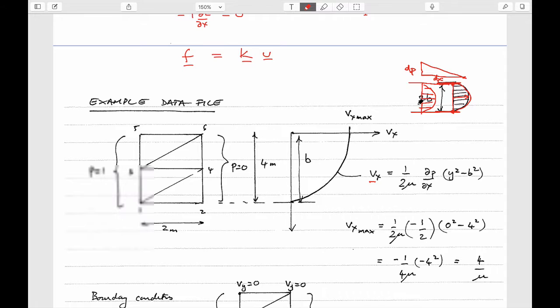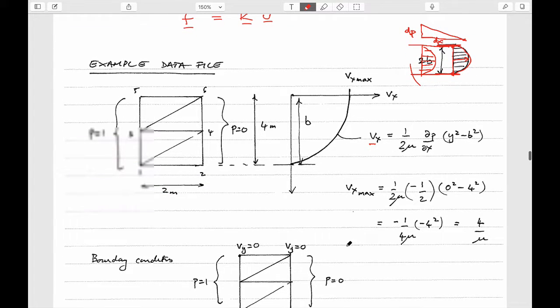And so the best analog I think is a deck of cards where you shuffle them over each other. They all shear relative to each other. And this shearing between all of these lamellae is the action of viscosity that builds up this force that you have to apply. So the force that you're applying due to the pressure upstream relative to pressure downstream is all being expended in terms of viscous loss, through this equation.